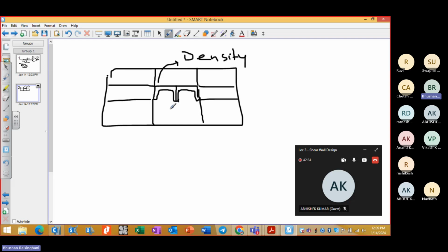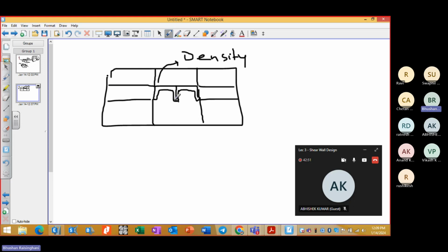So that also needs to be checked and proved that 100% forces are getting redistributed on the perimeter, and the connected elements will transfer the forces from core wall to the perimeter. So perimeter and core wall have to be adequately connected so that the first mode is not torsion, and also the torsion does not dominate the design of the building.